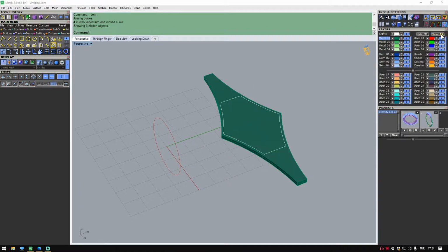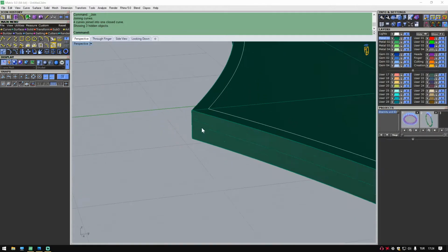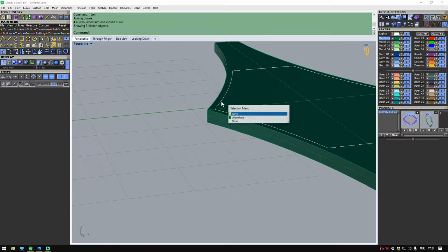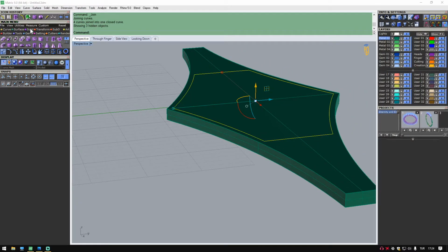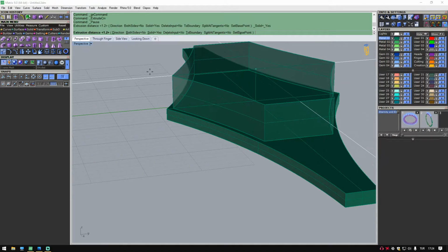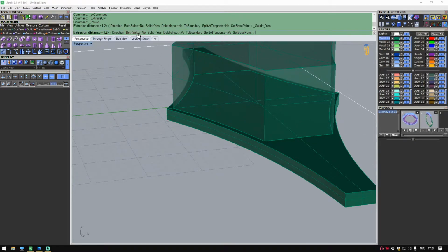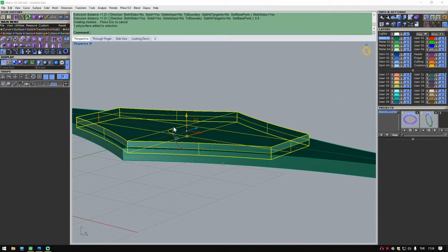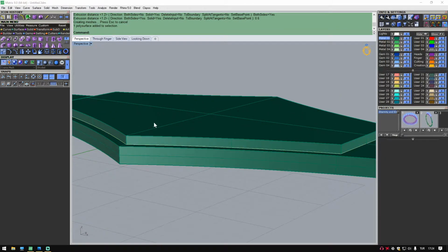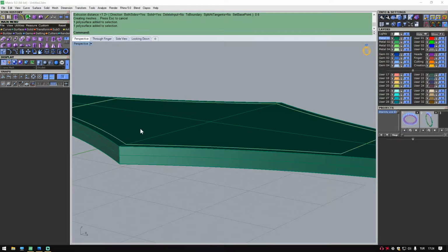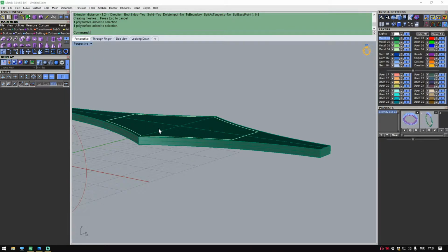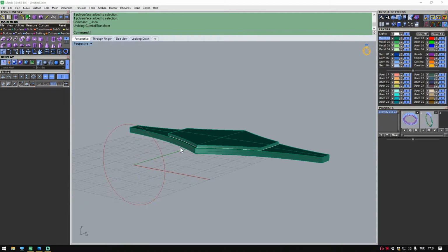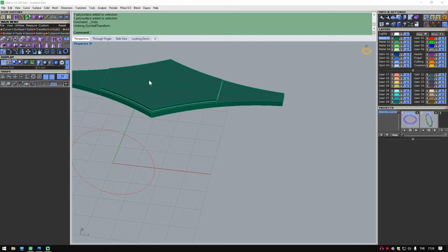Let's show the poly surface back. Okay, now we extruded this piece 1.2 and I want to carve half of it. We'll select this curve, go solid, extrude, and we'll extrude this 0.6, which is half of 1.2, but I want this to be both sided, 0.6. Why? Because sometimes if you don't have a piece going up there and it's just like so, it doesn't do the difference, you can't carve it. Sometimes it has a problem like that, but like this you never have a problem.